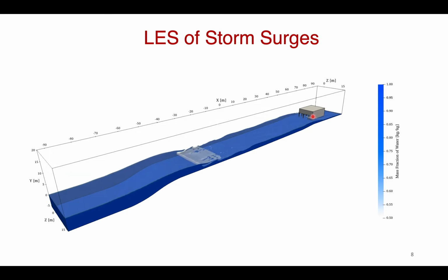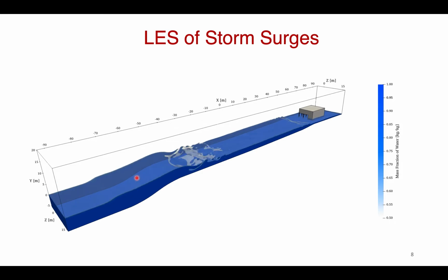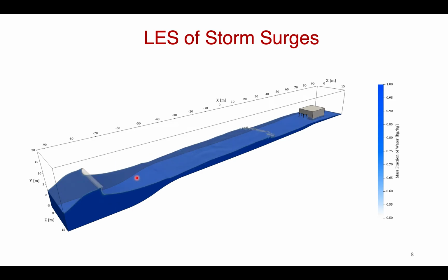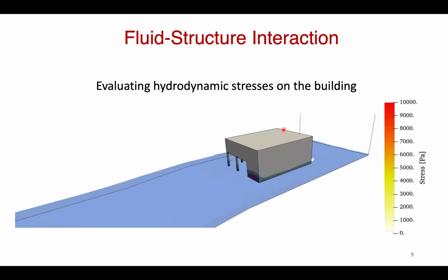So we took one building there and calculated the geometry and the bathymetry, and then we created these waves. We wanted to see how these waves propagate and how dangerous they are, especially large waves. When the wave height goes beyond 6 meters, they become very, very dangerous. You see these large eddies and different turbulent eddies that are being resolved very well in the large eddy simulation technique, and that is something we cannot get using RANS and commercial software. Here is a zoom in.